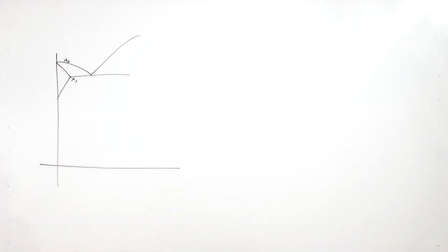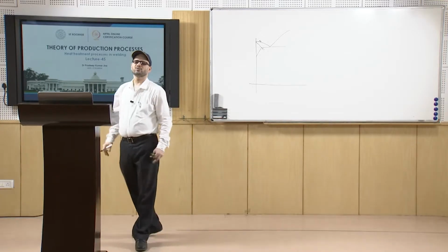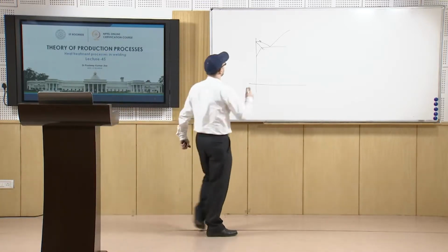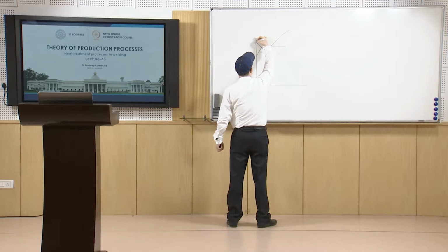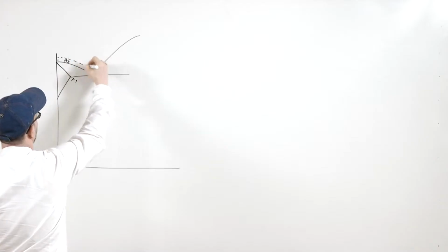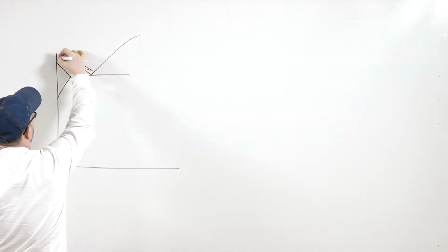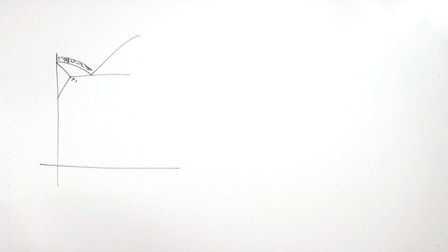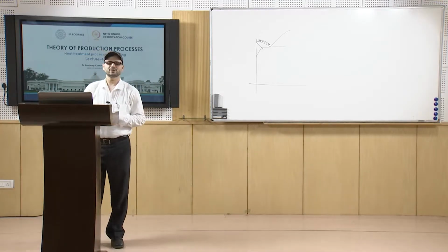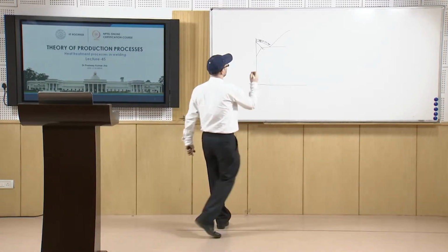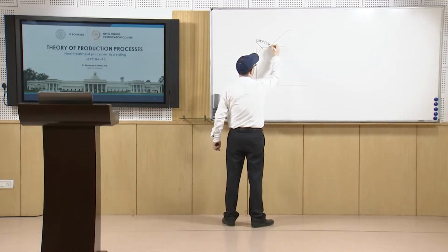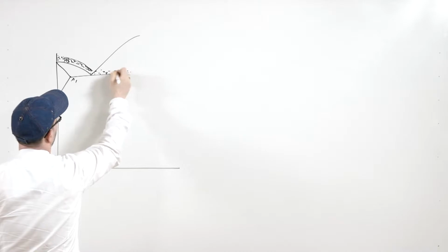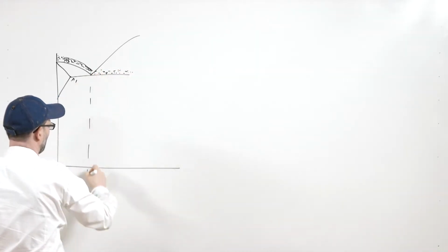Now, whenever we have to heat treat, we go a little bit above the upper critical temperature. Normally this annealing is done in this temperature range. So, this is the zone where we go for the annealing purpose, and this is your 0.8% of carbon. Once we have to do the annealing of these hypereutectoid steels, we go in this zone. So, this is your 0.8% carbon.